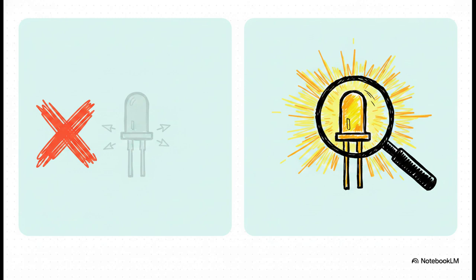A generic default LED might show a voltage drop of around 693 millivolts. But our sources point out that is just not realistic for a standard visible LED. It really should be closer to 1.7 or 1.8 volts. With LTspice, fixing this takes 2 seconds.